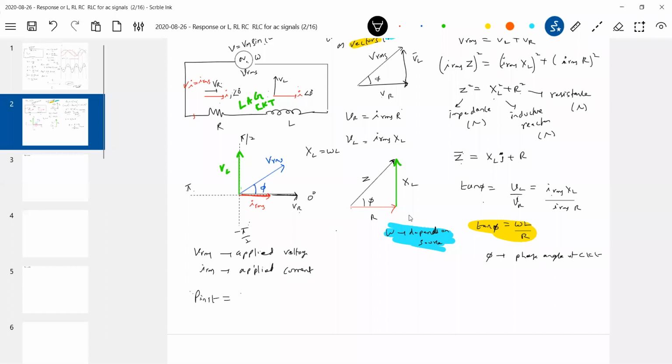So here, V into I. V should be equal to Vm sine(omega t plus phi), and I is Im sine omega t. Is it justified writing sine(omega t plus phi)? Because current lags the voltage. So this should be equal to Vm Im sine omega t, with the expansion of sine(omega t plus phi): sine omega t cos phi plus cos omega t sine phi.